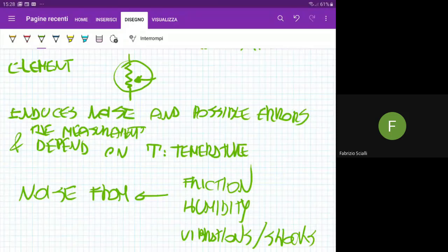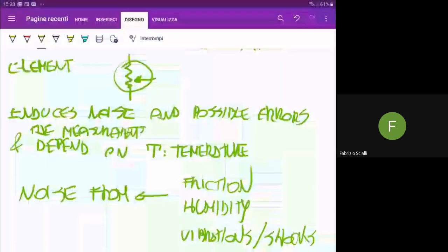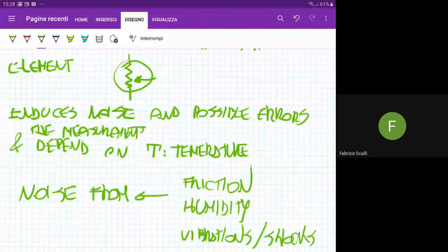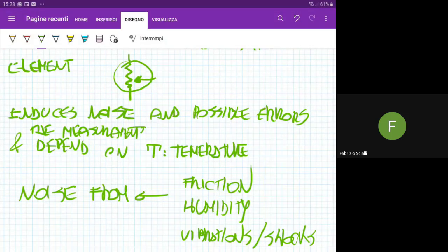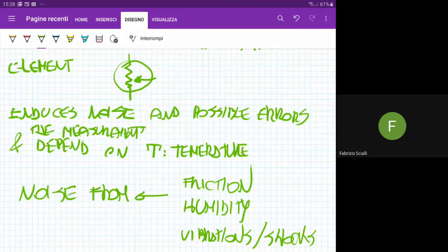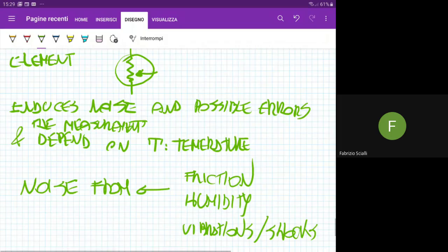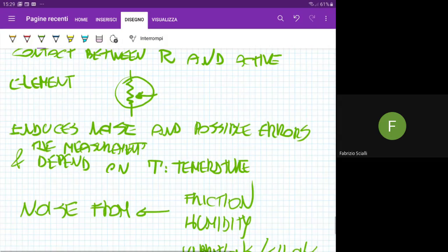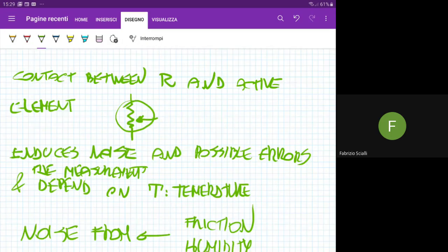We don't like that. It is too complicated in the actual field to take measurements like that. How can we overcome this problem? Just look at the equation. We found that if you use a measuring device with a large electrical resistance compared to the transducer resistor, the potentiometer resistor, we are happy because there is a practical linear relation. Not the real one, the practical one. And we saw a picture in which the deviation from linearity is about 10%